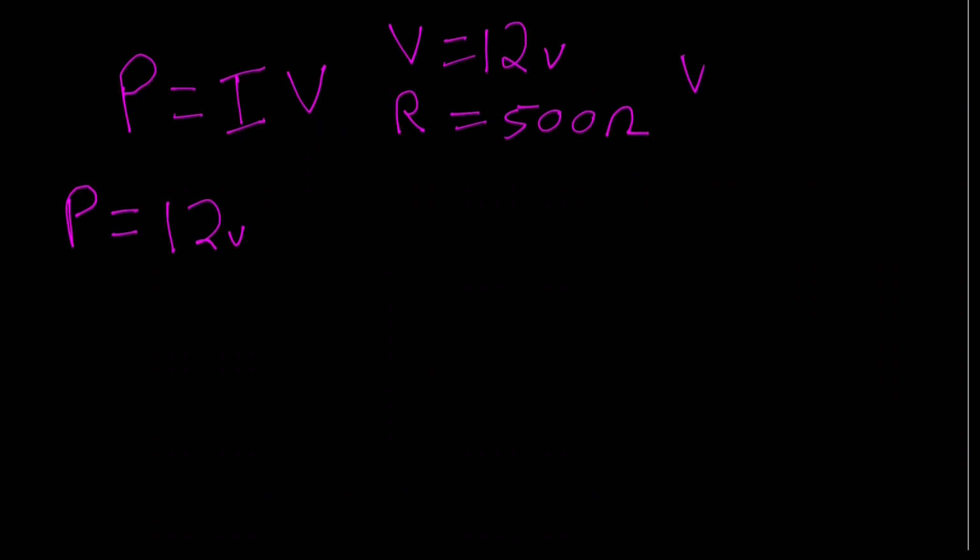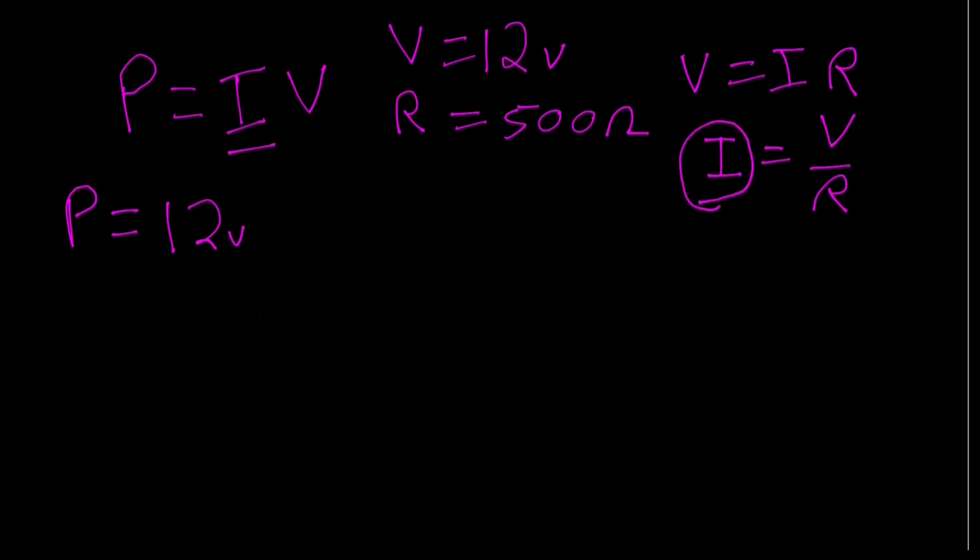And we go back to Ohm's law. So V equals IR, and if we're looking for current, you remember that we can rewrite Ohm's law as voltage over resistance. So that missing value of current is now right here. So that current is going to equal voltage over resistance.